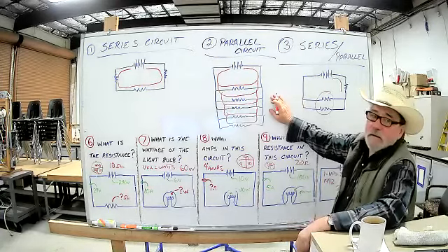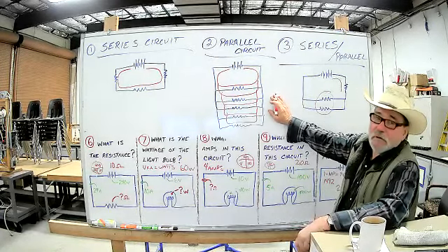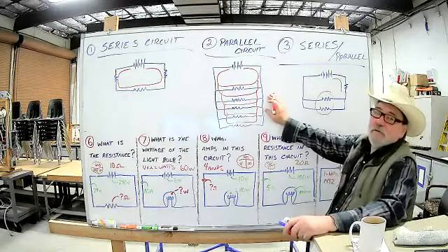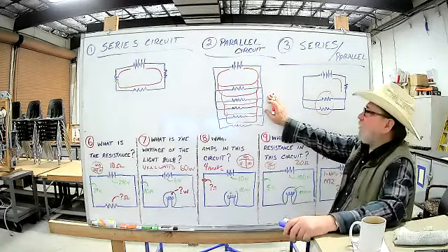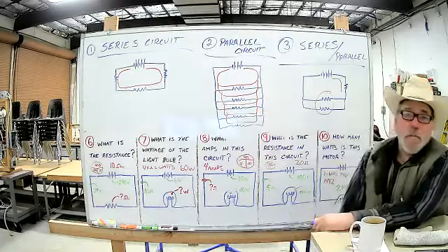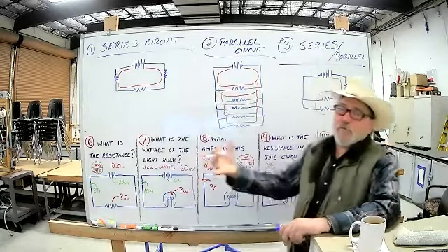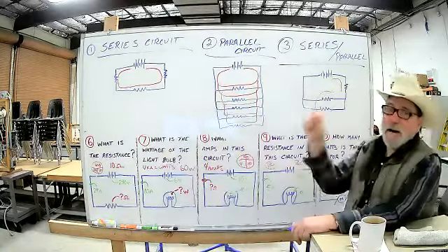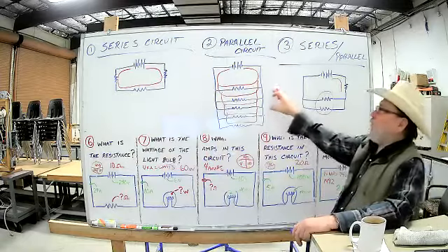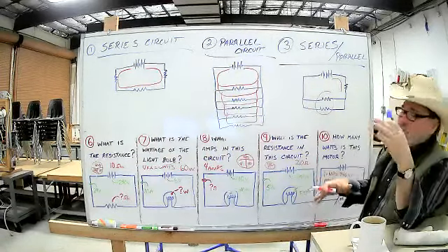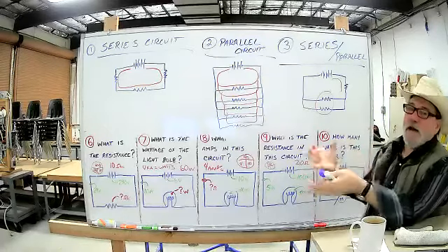Parallel circuit, it has multiple paths to flow. That just depends on how many you want to put in there. So therefore, your resistance is going to be less the more parallel resistors you put in. On a series, the more you put in, the resistance is going to be more because there's only one path for it to flow. Where this one, I mean, it can choose to go here, go here, go here. It's like one hose of water compared to 1,000 hoses of water.